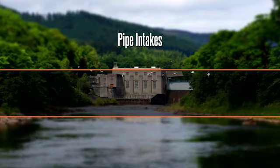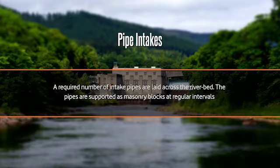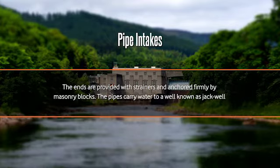Pipe intakes. When a small quantity of water is to be drawn, pipe intakes are economical. A required number of intake pipes are laid across the river bed. The pipes are supported on masonry blocks at regular intervals. The ends are provided with strainers and anchored firmly by masonry blocks. The pipes carry water to a well known as the jack well.